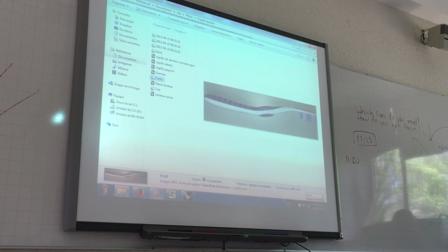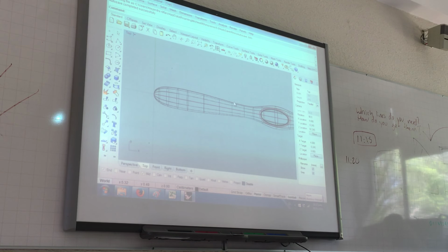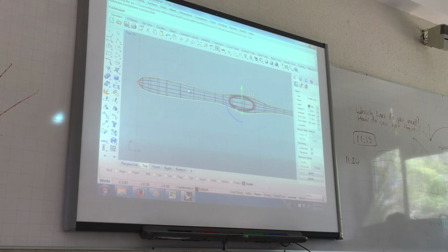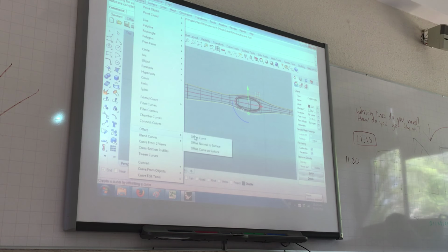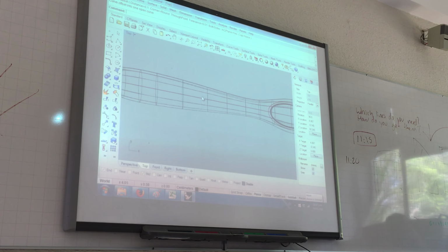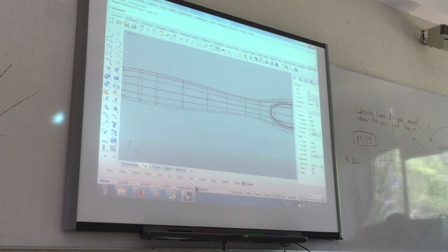So to do it, I'm going to do an offset to the curves that I already have, to this and this. I'm going to use this to do the projection. But since this is in the edge, I can use it. So what I'm going to do is an offset of this on the inside. Do you see it? I'm going to change it to the red layer so that you can see what I did. There. Let me switch to the red layer.